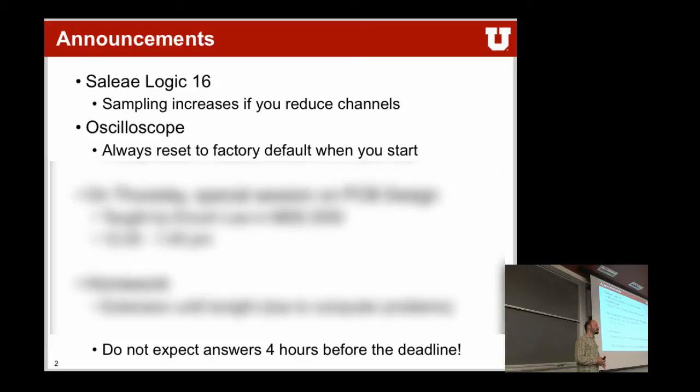Another tip that's always good for oscilloscopes: before you start using them, reset them to factory defaults. You never know what state the oscilloscope is in when it comes up, who used it before, or what settings they put in. If you're completely lost, reset to manufacturing defaults. That way you know the state of the scope. It's usually a pretty decent state, and from there you can dial in whatever you need to use.